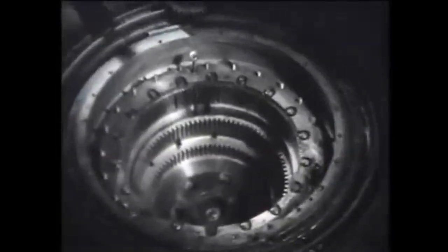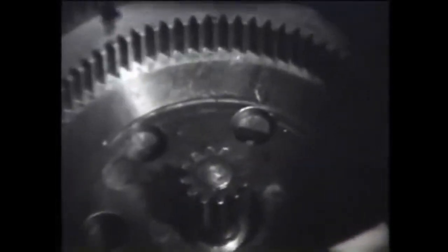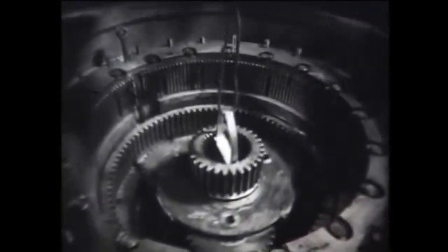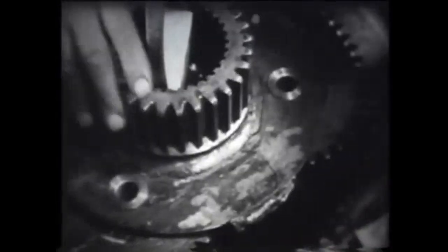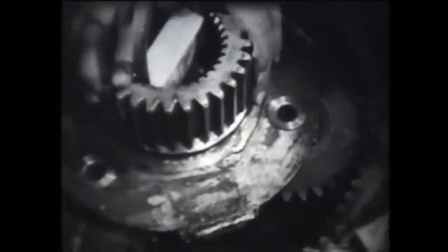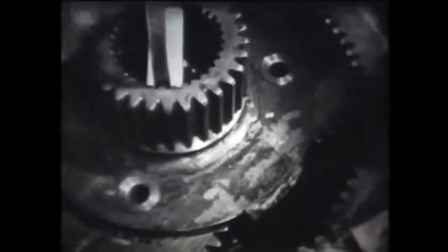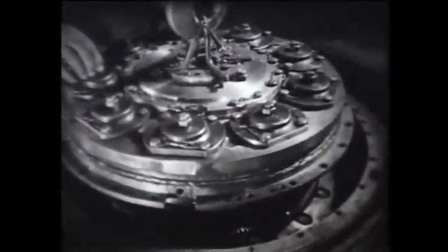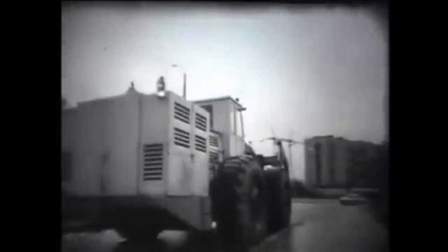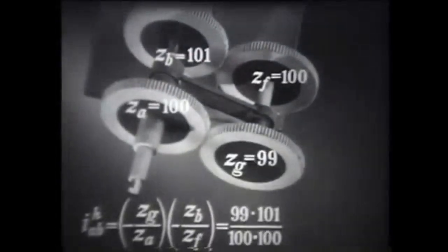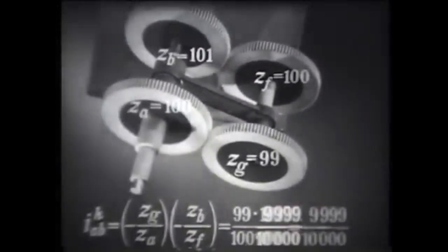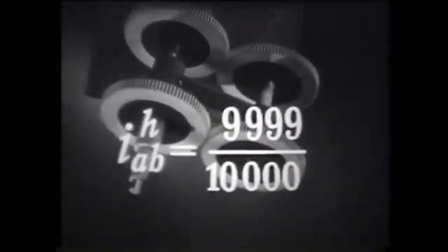The advantage of planetary gears is that they are more compact than mechanisms with fixed axles. So, for example, the entire drive of the log loader movement can be placed in the motor wheel. If the gear ratio of the differential is driven close to 1, then the gear ratio can reach 10,000, but the efficiency is very low.